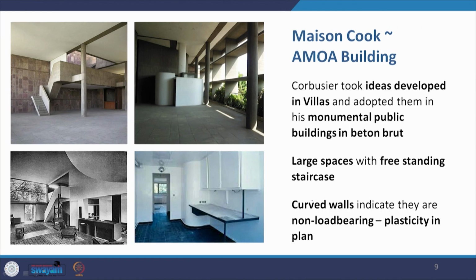Now Corbusier took the ideas developed in the villas and adopted them in his monumental public buildings in Ahmedabad. We have already seen that in Chandigarh. So there are large spaces, for example, with a freestanding staircase. You find that in the Mill Owners, and you find that in Maison Cook or Villa Cook, and then you have the curved walls in Mill Owners, and you have it here also in Maison Citroën. So these curved walls are indicative of their non-load bearing nature and thus plasticity in the plan.